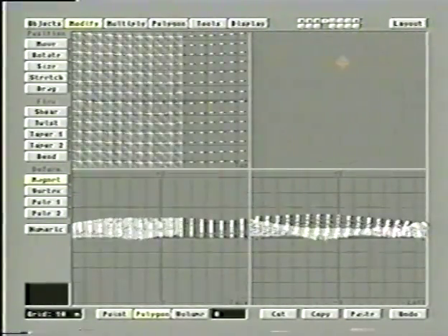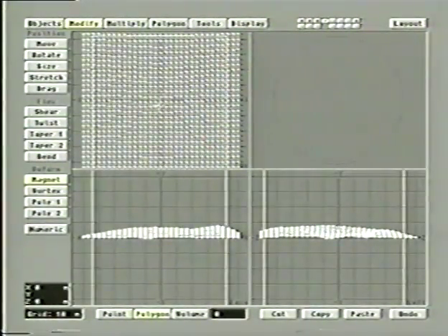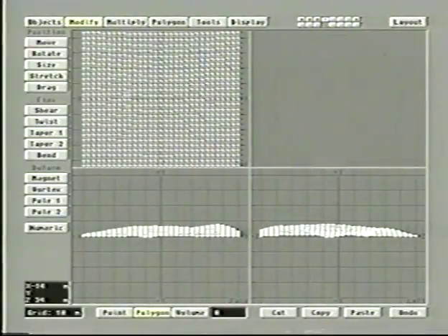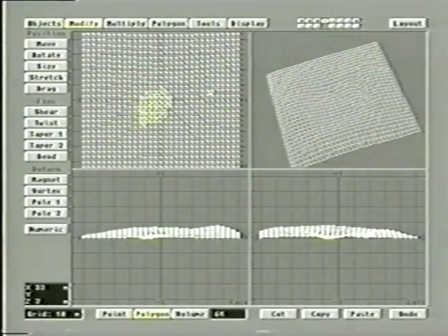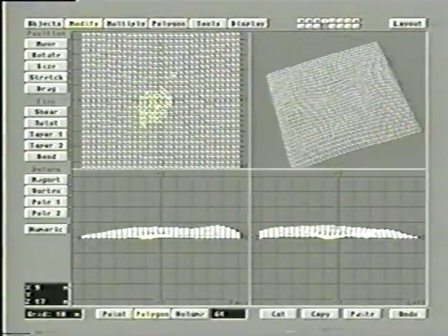Now what I'm going to do is back myself off a little bit, and I'm going to pick a bunch of the polygons in the middle. Because remember, this is where I'm going to have a house or something like that. So I pick a bunch of these polygons, and I'm going to use a function called set value. Now what set value does is it forces whatever you have selected to move to a certain value. What we want to do here is take these polygons that we've selected and force them to be at 0 on the y-axis, up and down. Pretty straightforward. But this will make it so instead of trying to nudge it into place and, gee, I hope this is right, this will force it down at 0.